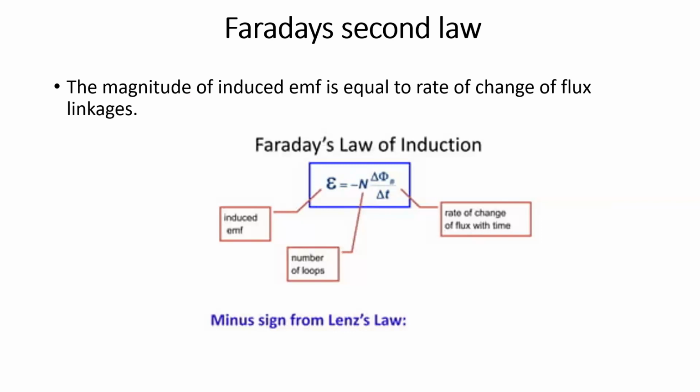So in the case of a motor, the speed will get reduced, because the produced EMF becomes a counter EMF, back EMF, and it opposes the source itself. That becomes a drawback in a motor. EMF should be generated in a generator. If EMF is generated in the motor, that becomes a problem, like Lenz's law, minus.